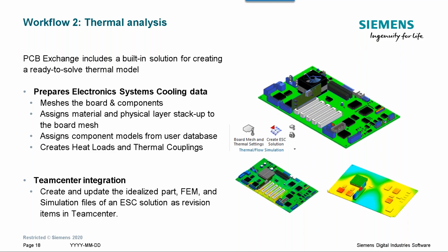And here's what exactly we do in this case. And we'll go into more details into all of these steps. So first of all, we mesh automatically the board and the components. We assign material and physical layer stack up for the board mesh. We assign the component models from the user database, and all the boundary conditions and couplings are also created for you automatically.